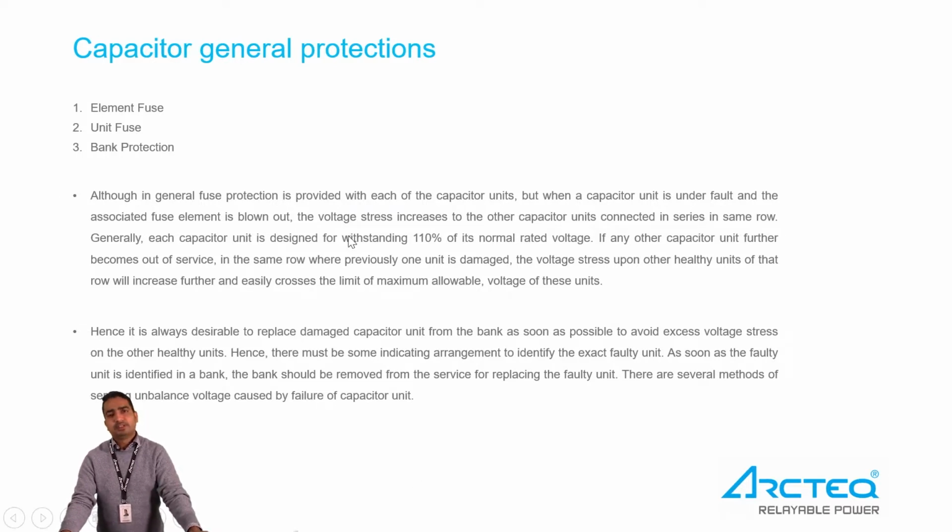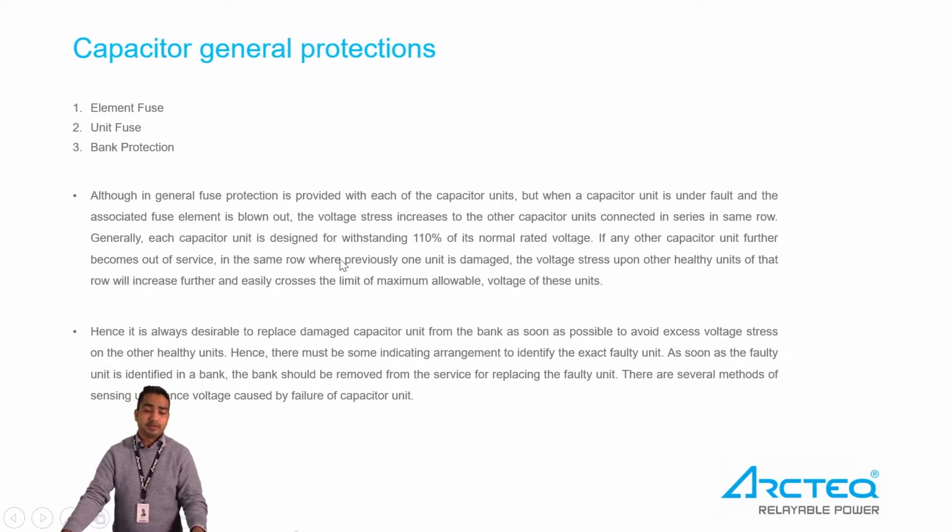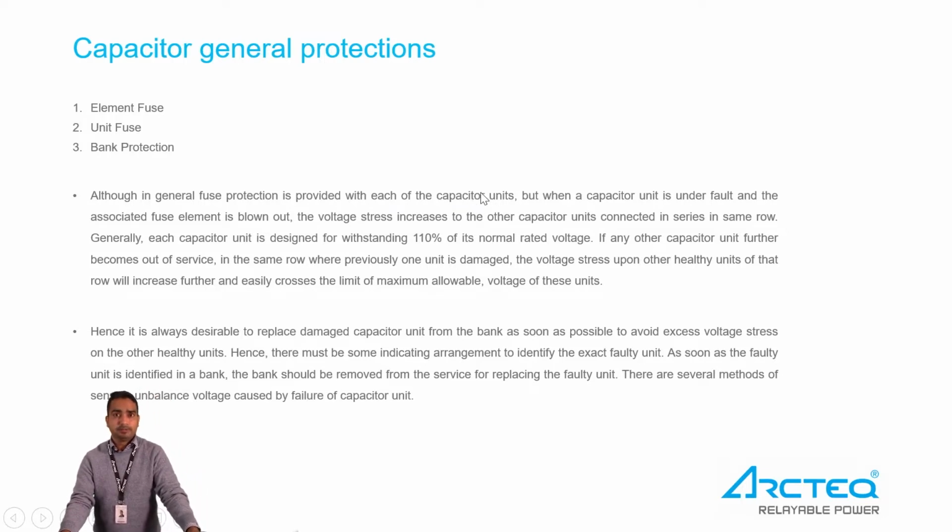The capacitors are designed to withstand 110% of the nominal rated voltage. So normally, under normal conditions, they are all working fine, but when some get removed, then the whole string gets stressed.